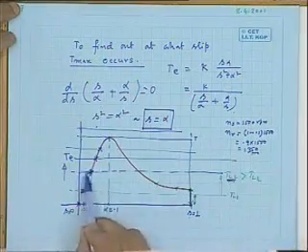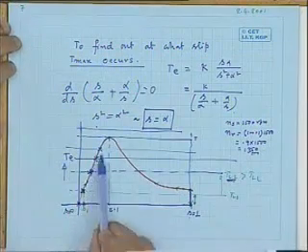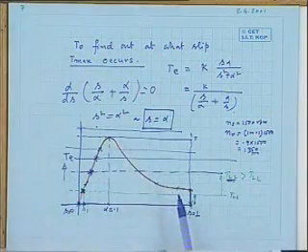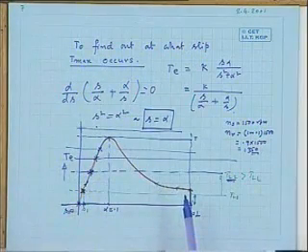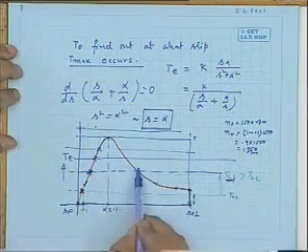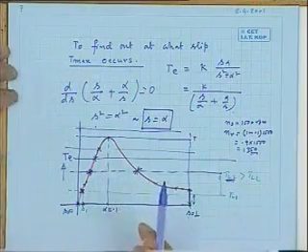Achha, now I will ask you one question. As you can see, suppose this is TL2. See, machine can operate steadily when electromagnetic torque is equal to the load torque, is it not? If you look at the points of intersection that your load torque makes with electromagnetic torque, where electromagnetic torque will be equal to load torque, there are actually 2 points, this one and this one, is it not?